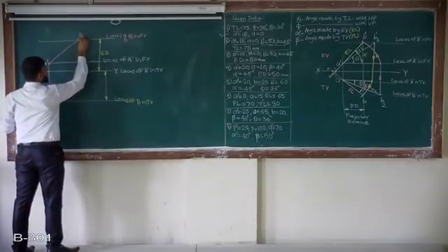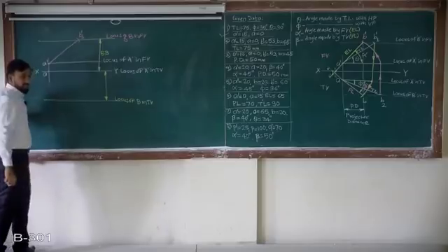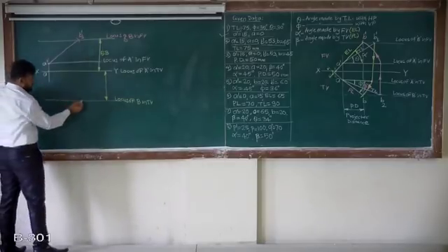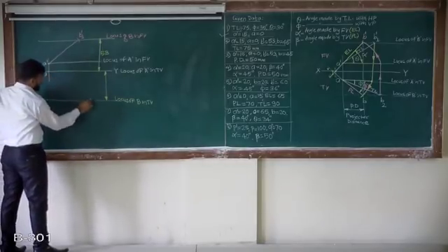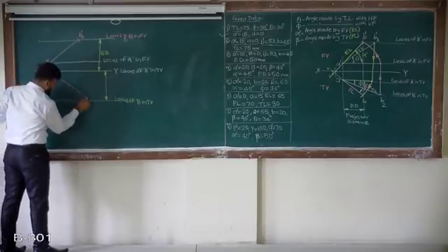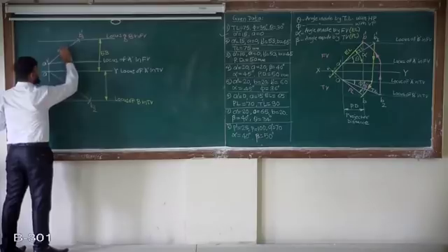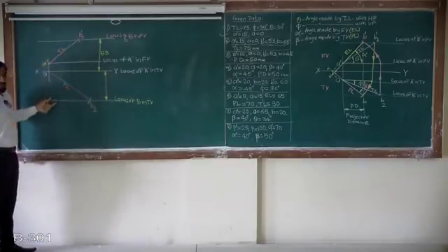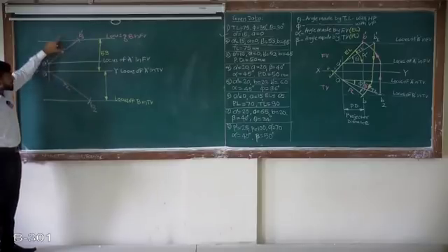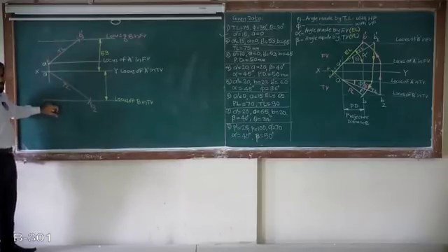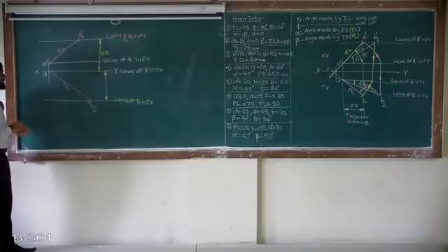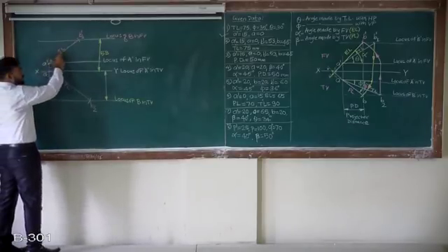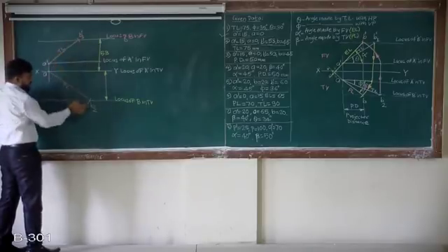This point is B1 dash. Same, I know this locus also, so mark the true length and join it. This point is B2. The length is true length. So both are true lengths because we know the locus of point B in front as well as top view. Then it is a simple problem, once again I know the true length because I know the B1 dash and B2 locus.